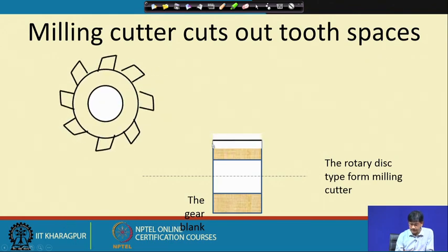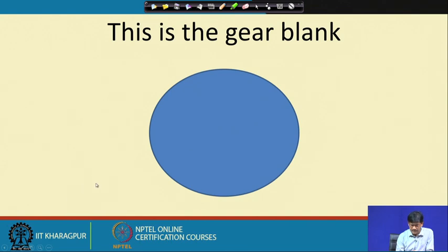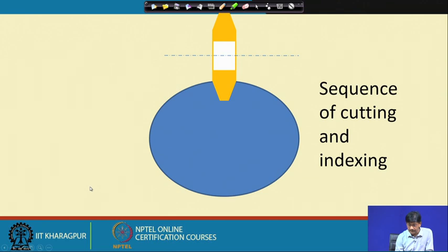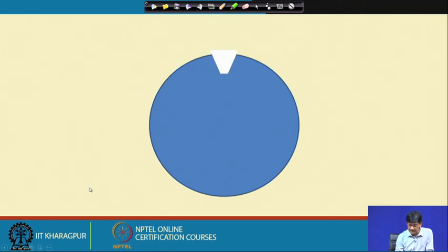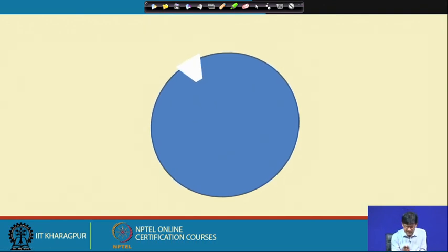That is it. This white portion shows the material which is removed by this cutter, which moves right through. So, how is this done? Now, let us see the other view. This is the cutter. Okay. It cuts the material. Then this is what you do by indexing. You shift it exactly by 1/71st of a rotation, so that a new portion has come, the cutter again appears and removes it. Please consider the drawing, because it is not very accurate. Okay. So, this is what we are doing.